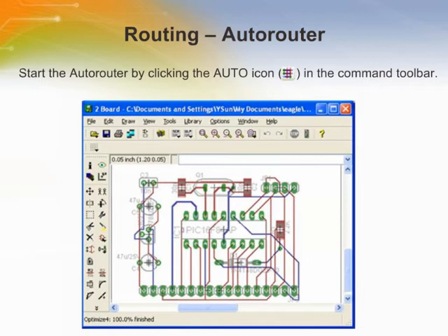In this dialog, you can set the design rules. The default parameters will produce a double-sided board. The Autorouter can be restricted to work in only one layer by selecting other layers as not applicable. This may, however, generate some errors since some components, surface mount devices, are not routable on the allowed layer.